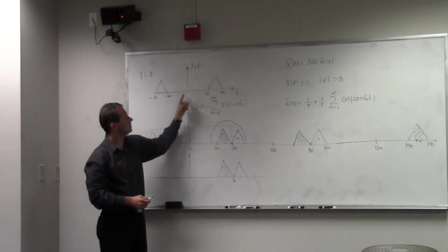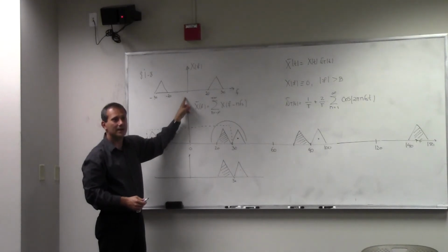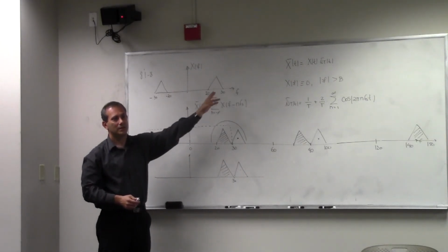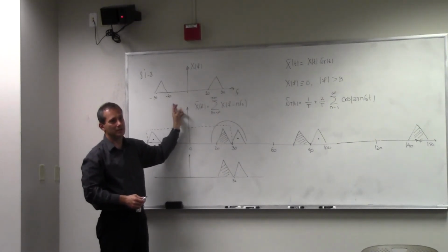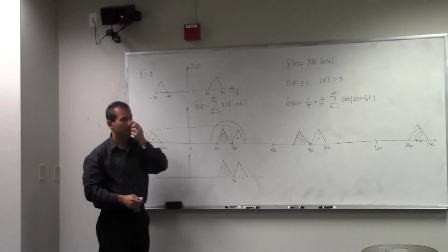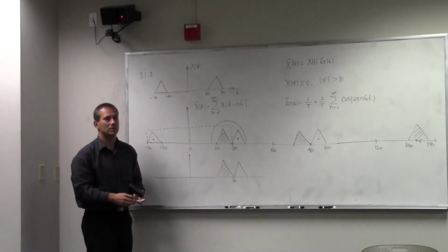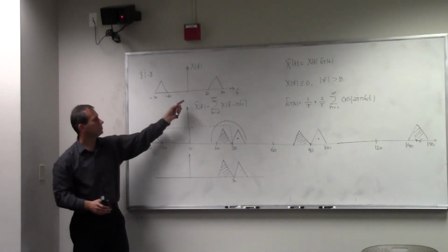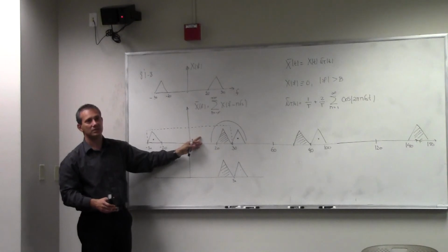Because when I shift this to the baseband, the bandwidth of my signal is going to be only 5 kilohertz, right? And then I sample with 10 kilohertz and send it wherever I need to send it. And then once I demodulate it, I shift it back to baseband or to the bandpass, right? So there are other schemes for how this can be done. Rarely when the signal is like this would you actually sample it at 60.